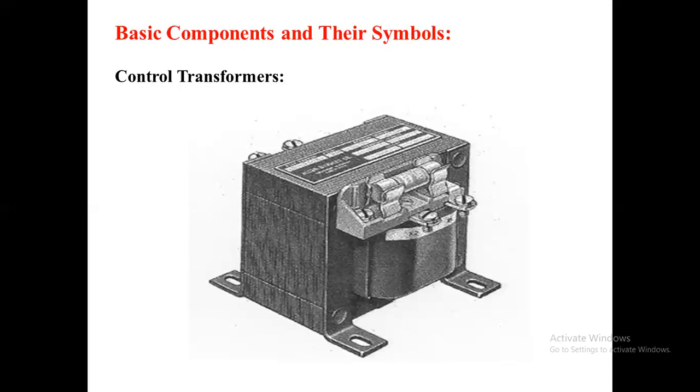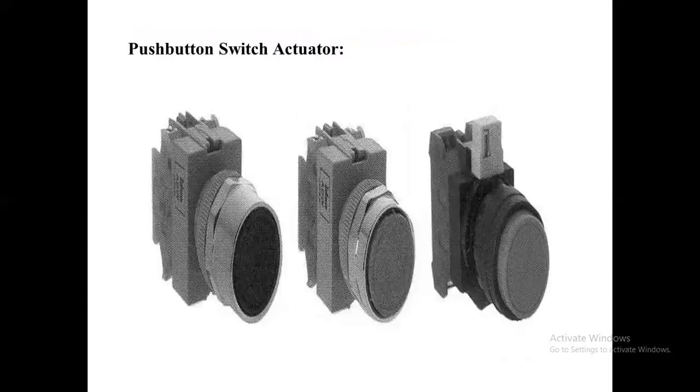The secondary windings are generally rated at 120 volt AC, 48 volt AC or 24 volt AC. By offering a control transformer with dual primary, transformer manufacturers can reduce the number of transformer types in their product line, make their transformers more versatile, and make them less expensive. This is all about the control transformer used in the PLC system.